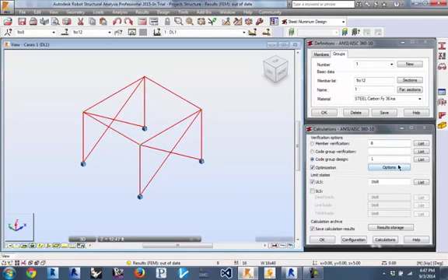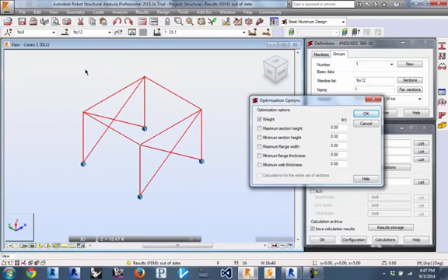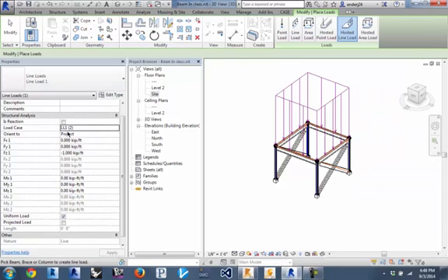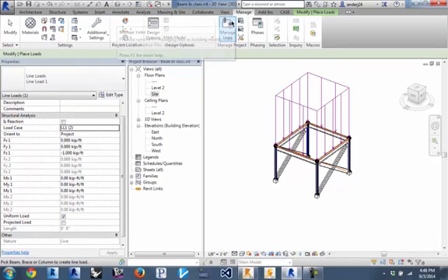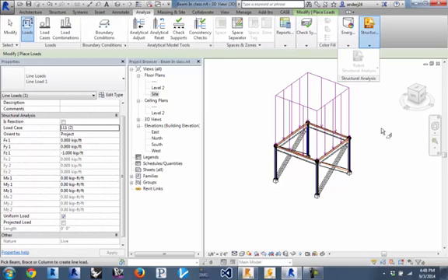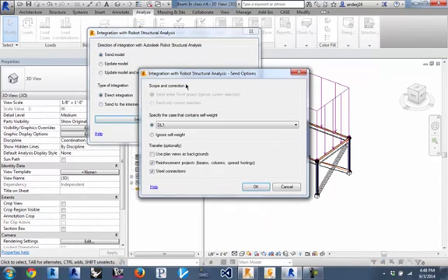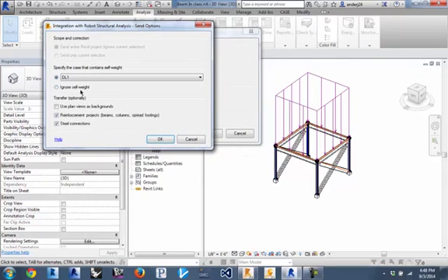So if you put a floor on top of that frame, it would account for the weight of that floor system, rather than you having to calculate the weight of it and count it into dead load. Yeah, it should. But the dead load is a separate load than the actual weight of the concrete and the composite deck, right? If you're using the definition from Revit, that is 3 inches of concrete on a 2-inch deck for your 5-inch, all of that mass information should be built into the definition. But if you create your own floor, you need to make sure you have the mass information in there in order for it to have that information, right?